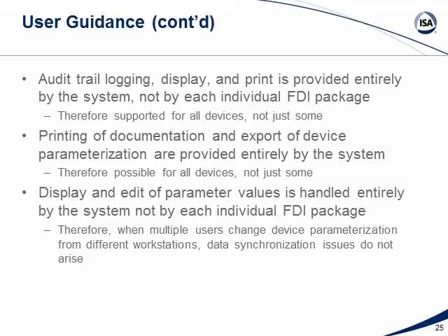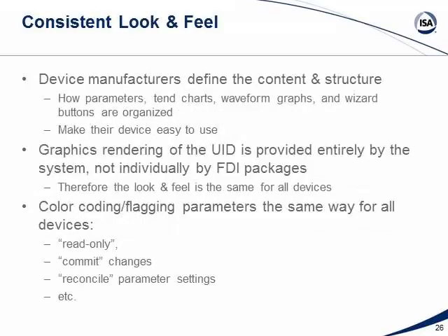Now some of the key enablers to make this all work, I talked about, are these hints that are provided in this DD package. When you're doing some of this integration, when a device supplier is writing his EDD as part of his FDI package, he's going to say, all right, let's pull up this display and put some text up there. Let's put a button, and let's put a chart up there that maybe shows a trend of the process variable, because maybe it'll help during this particular diagnostic related function.